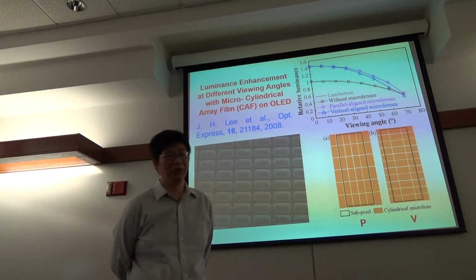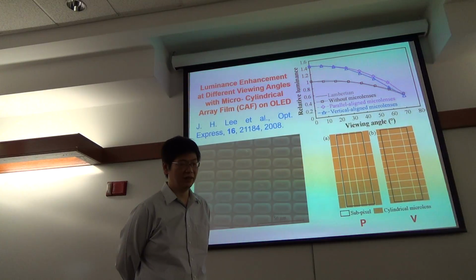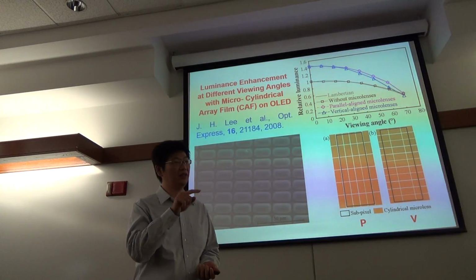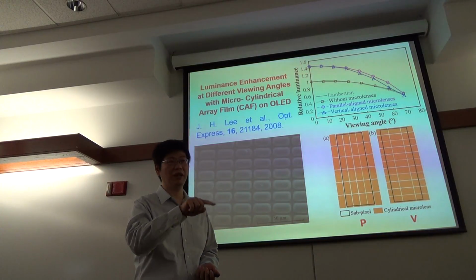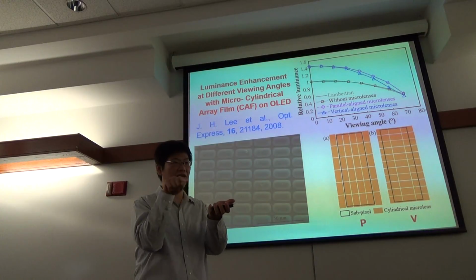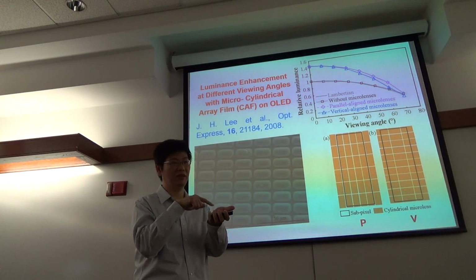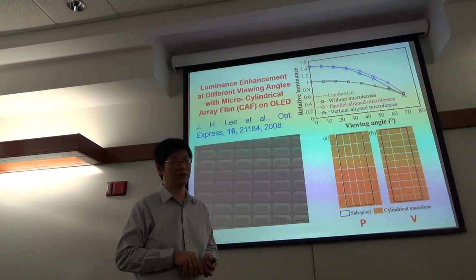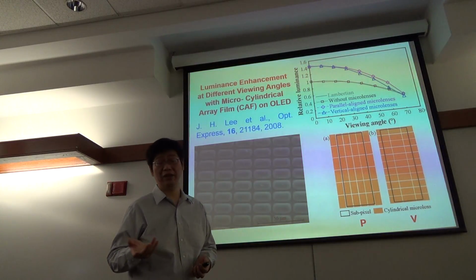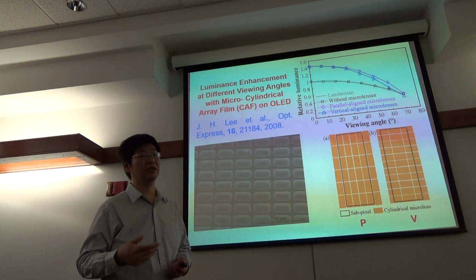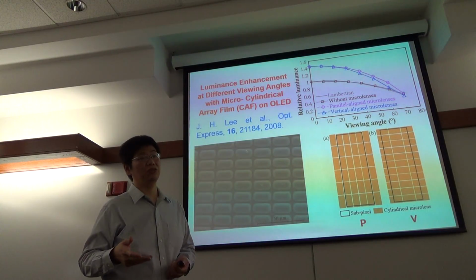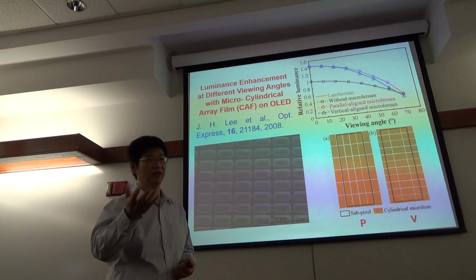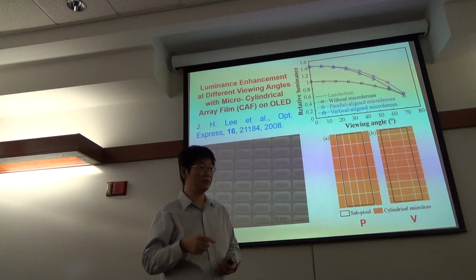Because for mobile, if you put some microstructure, the human finger can sense maybe 10 micron. So if it is 50 micron, when you touch it, you will feel it, and people don't like that right now. Another issue is if you do an external one, you have to consider the touch panel on top. So you have to consider the whole system.